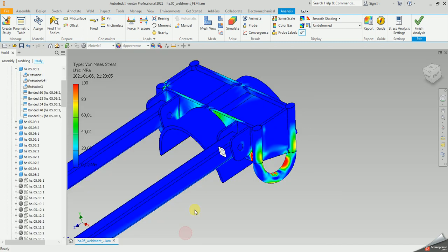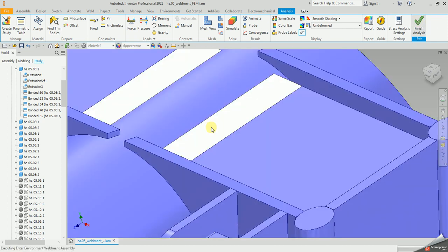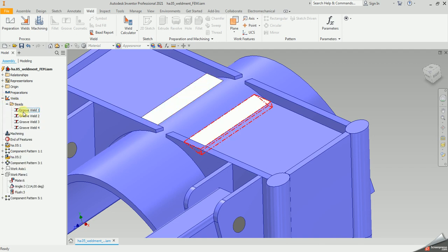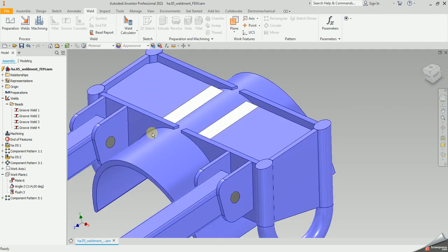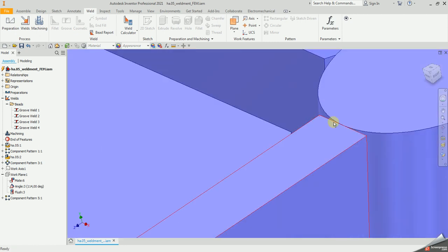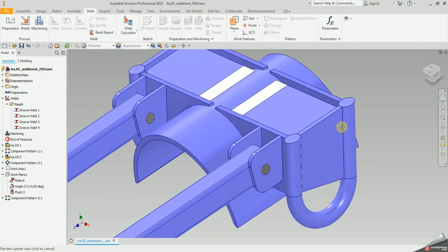And this is another sample of that. So if we go out, there are welds here because actually these elements do not touch. If I just, let's say, hide them, is it possible? No. So there is a gap because those plates are cut a little short, but otherwise I didn't model welds to fill those gaps between those elements because it's not really necessary. Also here, although this is just touching, going with the bonded contact is fully enough for this model.